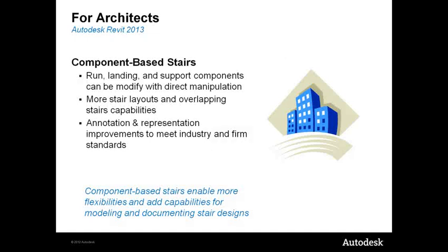You can customize the representation of a component-based stairs including symbolic representation, annotation, and graphic display. Some of the ways to customize stair representation include display treads and riser numbers, customize the cut line mark, and stair path annotation, defining graphic overrides for model or annotation subcategories. Bottom line is, component-based stairs enables more flexibilities and added capabilities for modeling and documenting stairs designs.